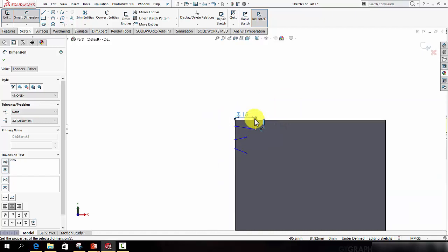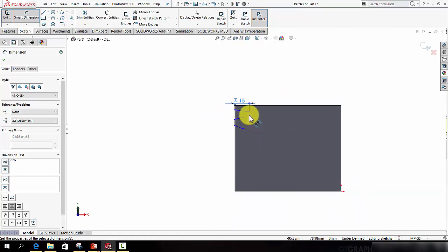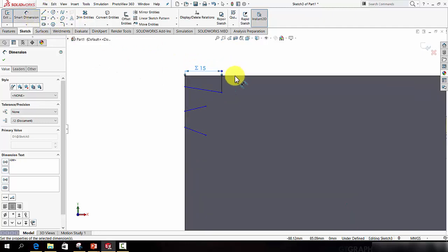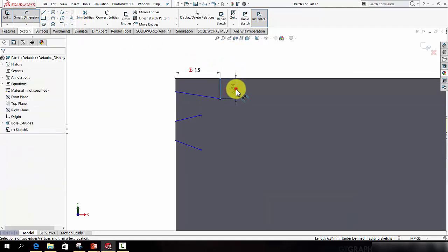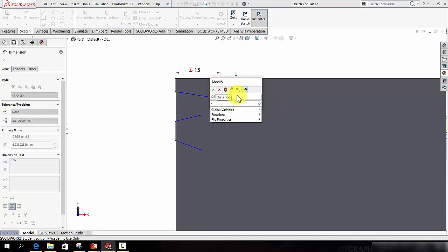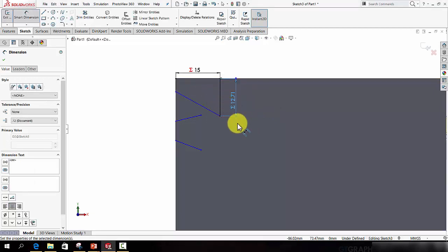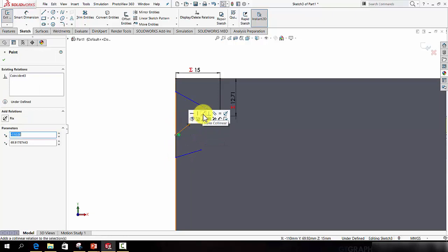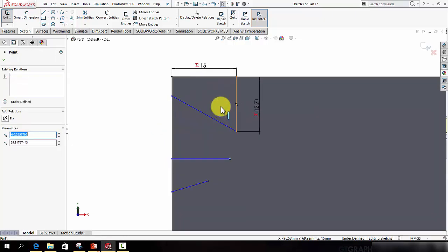When it comes to this line, I want the joints to be evenly spaced along the overall height of the component. So I need to link those. So to link those, I will set up a dimension for this line and use equals, box height, and in my case, divided by 7. So that means that that dovetail is always going to be 1/7 the height of the overall box.